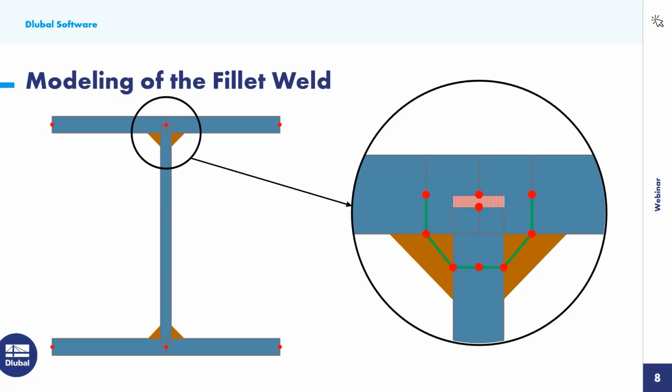The program generates the connection elements shown in green, which represents the fillet weld. This configuration results in a closed cell, which leads to a Bredt torsional moment of inertia being taken into account in the cross-section properties. The welds have a noticeable effect on the stress distribution.